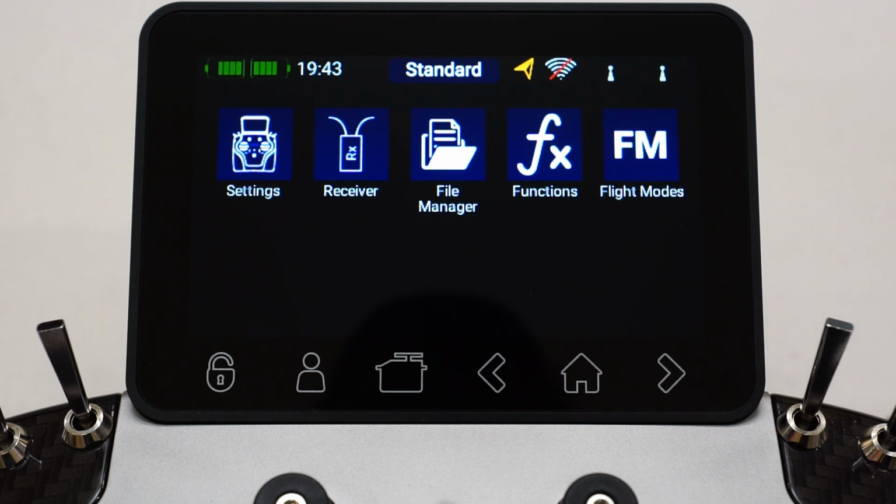So for a helicopter, for instance, we run different pitch depending on if you're in forward flight or hovering. Also, you probably have heard the term idle up in some cases. So that's an old helicopter term, again, probably from the late 1980s, early 1990s, where if you wanted to fly inverted or even just normal flight, you wanted some negative pitch on the collective stick, which is also our throttle stick. However, when you start your model, low stick is basically just idle, so the engine's just idling away. However, when you were flying a helicopter around in the sky, if you wanted to bring it down, you basically had to reduce the collective pitch, which you did with the throttle stick, but you didn't want the motor to reduce back to idle.